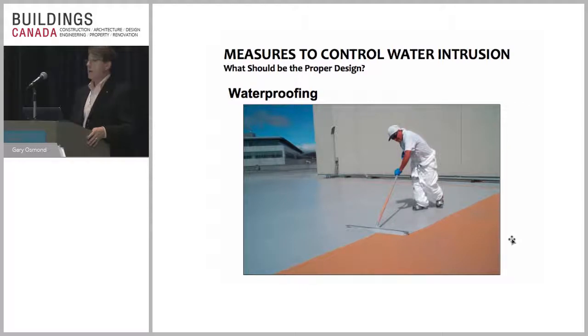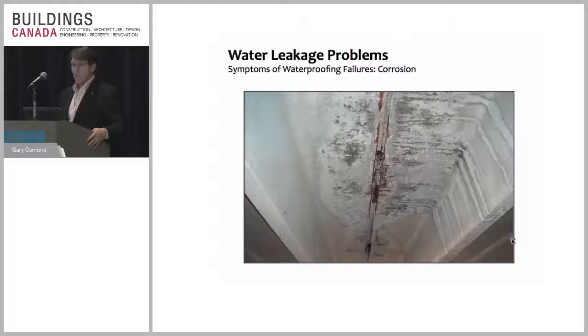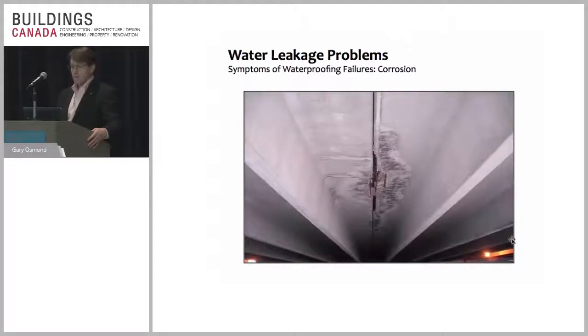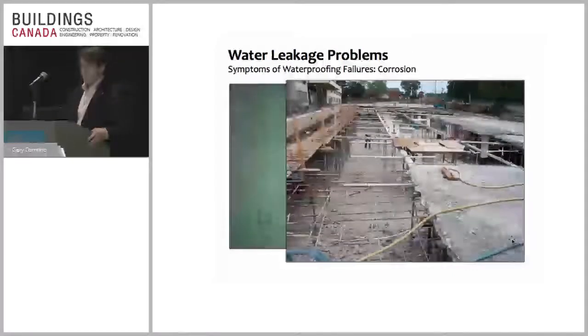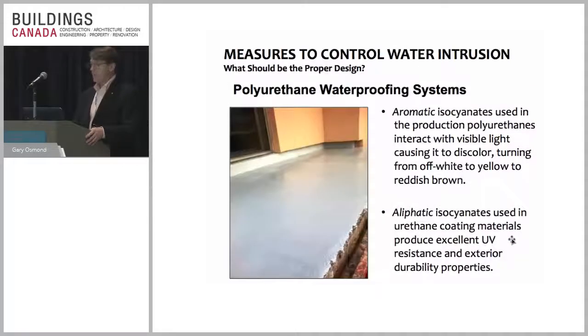Waterproofing options have certainly changed, and you have a variety in terms of acrylics or polyurethanes for waterproofing membrane systems. They are UV stable. Without it, we have problems. Water gets in, things happen, concrete breaks off, all sorts of cracks. There's cracks in these T-bars, and then there's real cracks. Things fall apart. Water gets in, breaks it down, you have a problem.